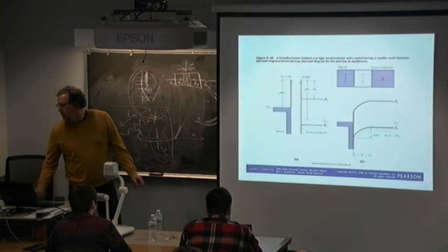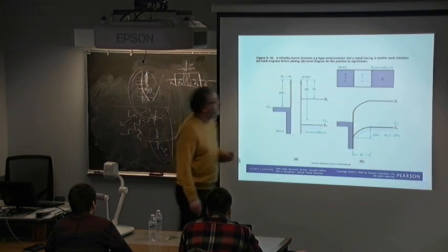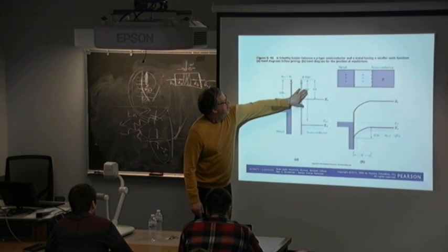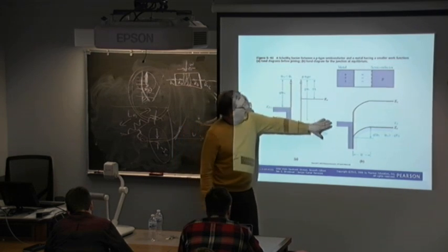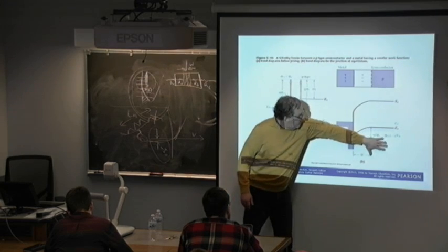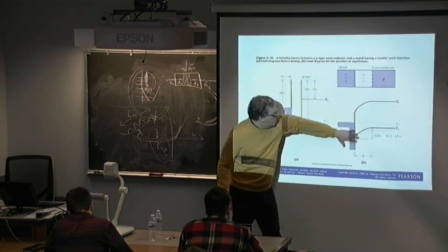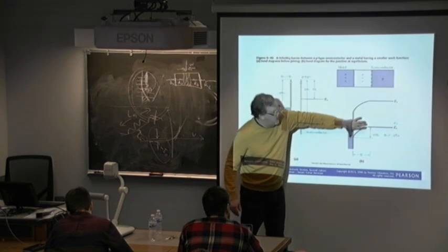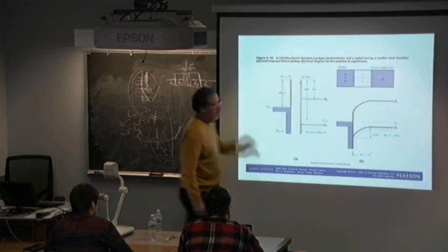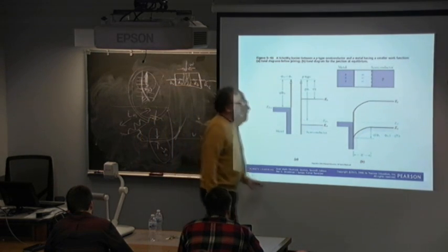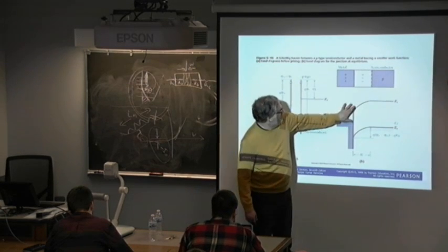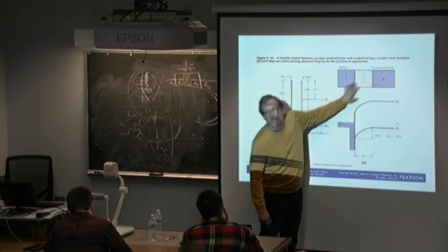So the P side is the same thing. I have a work function specified by the semiconductor work function and the metal work function, and I superglue those together. The holes wanting to come from this P-type material have to come across this barrier, and this barrier is non-trivial, so it inhibits and holds back the holes there. The metal is electron rich, and I still have a Schottky barrier height that inhibits the flow of electrons this way.